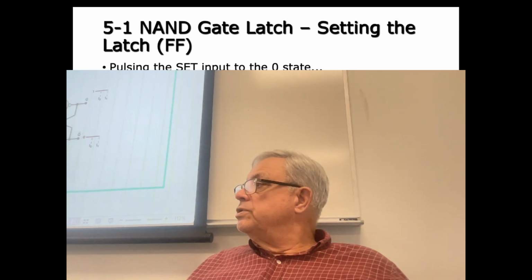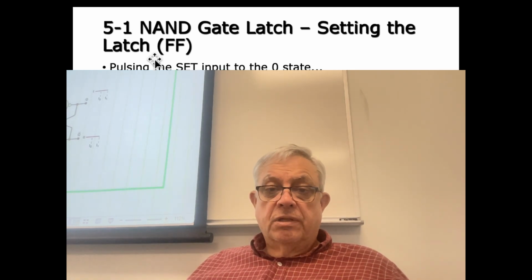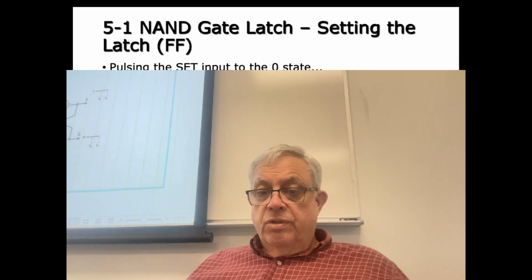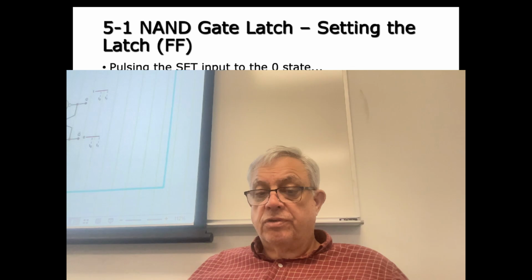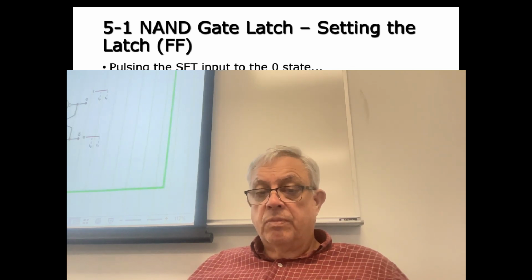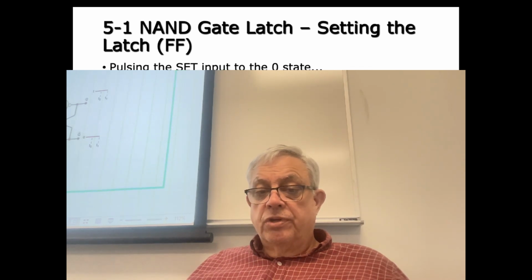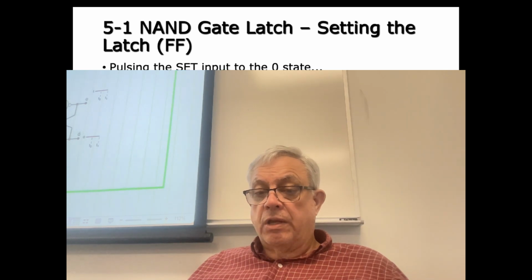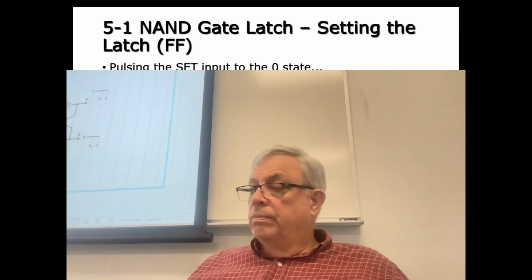Latches. Boy, did we have fun with latches. I'm going to stick with just the NAND latch as a latch. We had 2 NAND gates cross-connected, cross-coupled, so that the Q of 1 is the input to the second stage, and the Q naught becomes the input to the first stage. In this case, when I put a negative pulse here, that's the set that puts the output high. When this goes high, and this is already high, then this is going low.